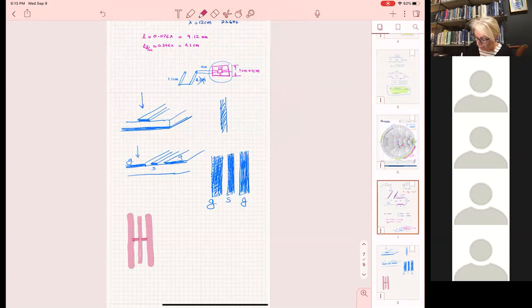You take the center, the signal line, and you short it to the ground. This is a short. It's a short circuit rather, as opposed to being a stub in this particular case. But it's a short. So it's easy to short things on one surface when you have a coplanar waveguide.